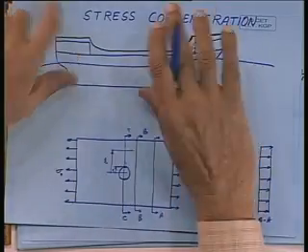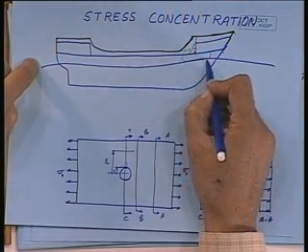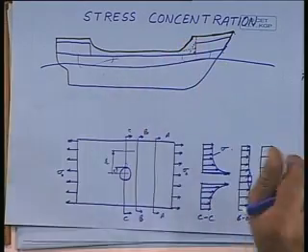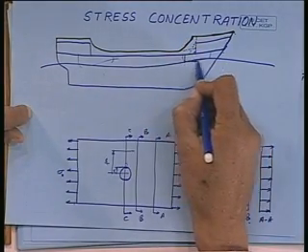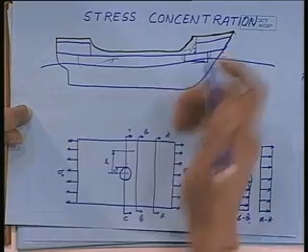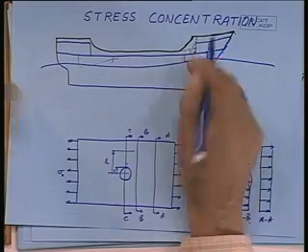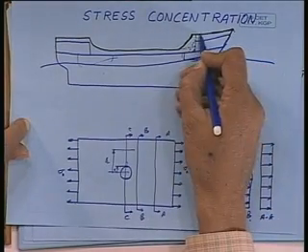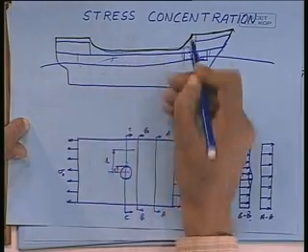The same is the reason when we are trying to do this. Now this particular ship will be under bending, so what will happen? This particular plate will be under stress, tension, compression, whatever it is, and this part of the shear strake we would like to strengthen. That is the reason why this plate is not given in this fashion, because this will also be subjected to that, and therefore we try to give an extended part in a smooth fashion here.